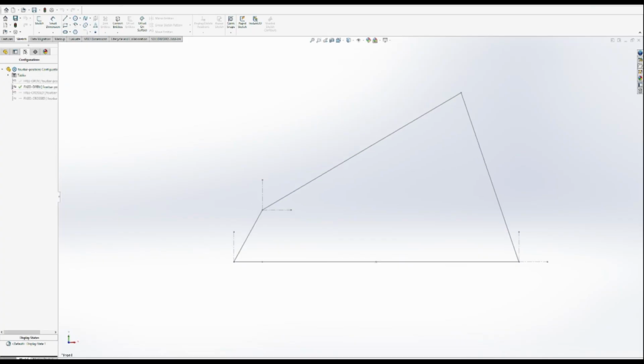So now let's go to our configuration where we have the position equations solved in SolidWorks. So this is our fixed open, and we know what our angles should be, what we predict our angles to be. So using our position equations, we predict that our theta 3 should be approximately 29.3 degrees and our theta 4 should be approximately 109.7 degrees. So let's go into our sketch and see if we get that.